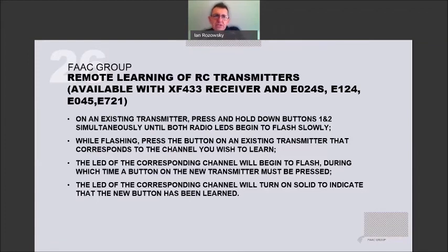One thing I just want to touch on that I don't think too many people know about, and that is remote learning of RC transmitters. Now this applies obviously to RC transmitters only, and it's available with the XF433 receiver on the E024, the E124, the E045, and the E721. What it means is if you've got a transmitter that is already working on a site, in other words an existing transmitter, you can use that transmitter to put the control board into a learning mode to learn another RC transmitter.